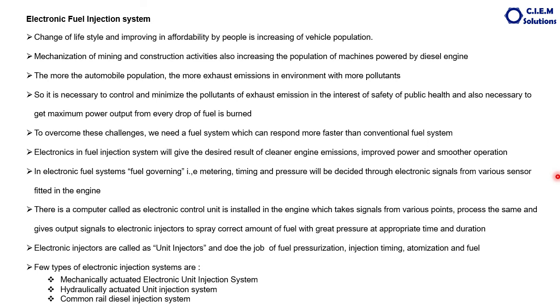The only thing a user has to take care of is to ensure that clean fuel is always supplied to the system. If the fuel is not clean, there will be more damage than in the conventional diesel system, because these parts are precision machined with close tolerances. If any impurities go inside the components, that particular component will be damaged. So necessary care has to be taken in supplying clean fuel.